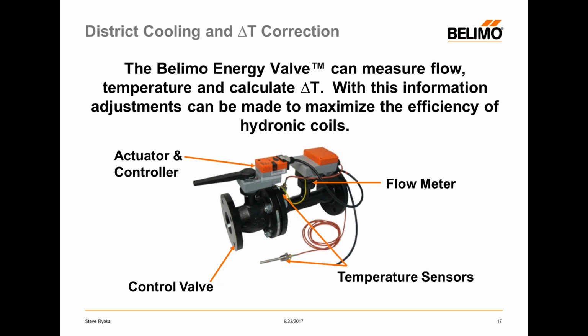The engineers who design these air handlers and these heat transfer devices have very specific parameters in mind, and they are best to be kept in accordance. Let's make sure our equipment works as it's designed. No different than any other mechanical device. You want it to run as efficiently as it possibly can. So again, what we do is we combine a flow meter, entering and leaving water temperature sensors, and some smarts in our actuator.